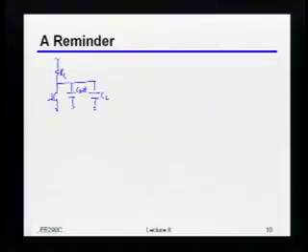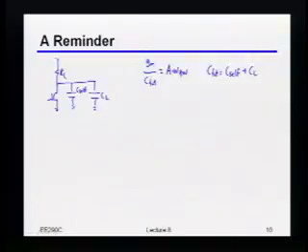Bandwidth. So when you say bandwidth, do you mean just the bandwidth, or is the bandwidth times something? Gain. Yeah, it's the gain bandwidth, right? So just as a reminder, if you do GM over the total capacitance, then that's of course just the gain times the bandwidth, right? Okay, well, that total capacitance is of course just the self-capacitance plus the explicit load capacitance. Okay?